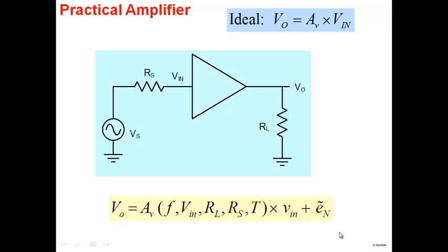So we see that in an amplifier, it's not just the voltage gain. There are many other parameters of amplifiers which are important, which tell us about these dependencies here, this F and Vin and RL and RS and all that. So what we have to do is understand what the important parameters of an amplifier are. If it were an ideal amplifier, all you need to do is say the gain of this particular amplifier is 100, and that's the end of the story. But because it is non-ideal, I have to specify the non-idealities. We have to have a measure of the non-idealities which are there.